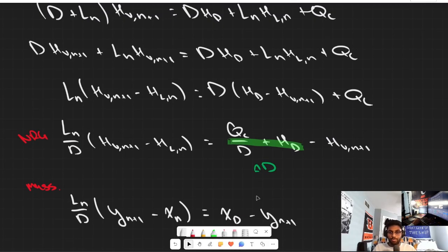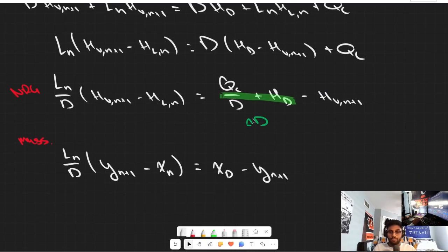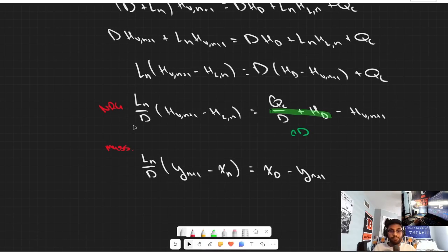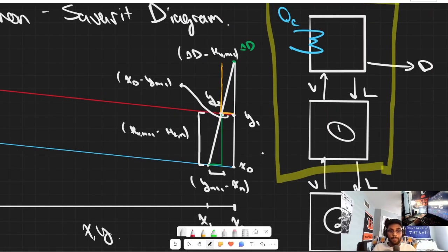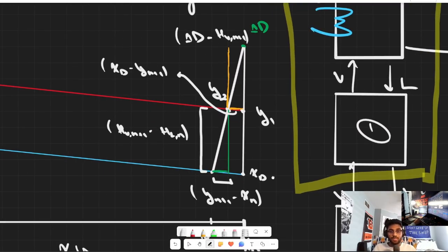And that is present right here. So all of this follows the energy and mass balances that we derived earlier. And we can see now that through this postulate of similar triangles, we have sort of proven that the straight line that goes across is defined by the differences in our enthalpies and the differences within our mole fractions.